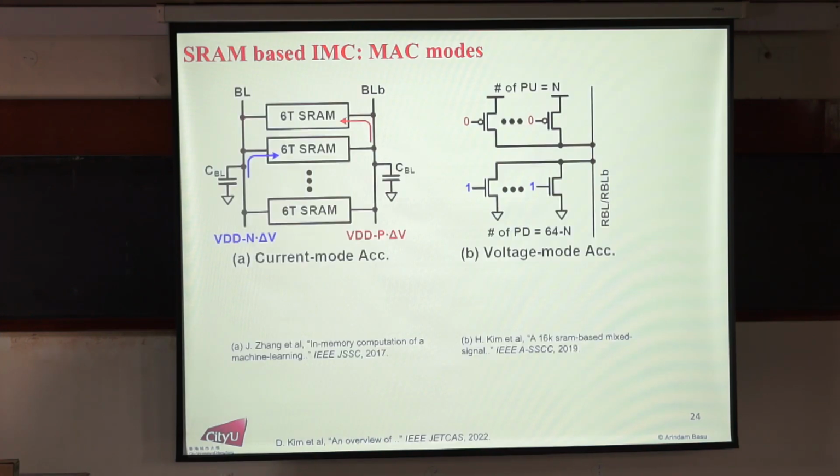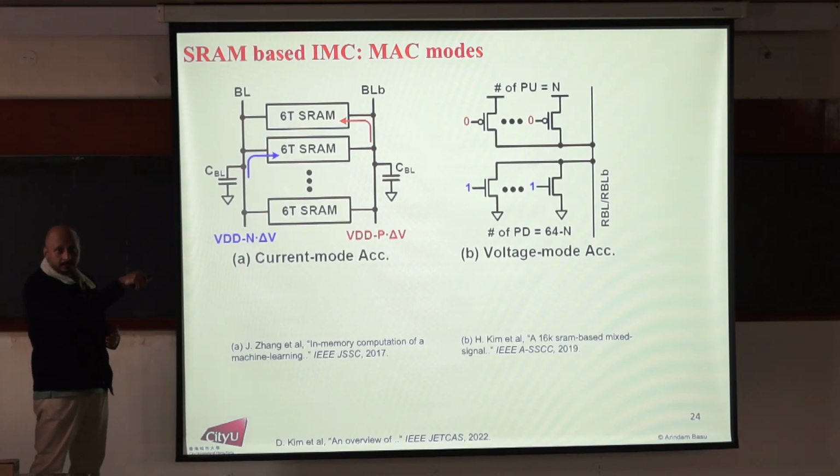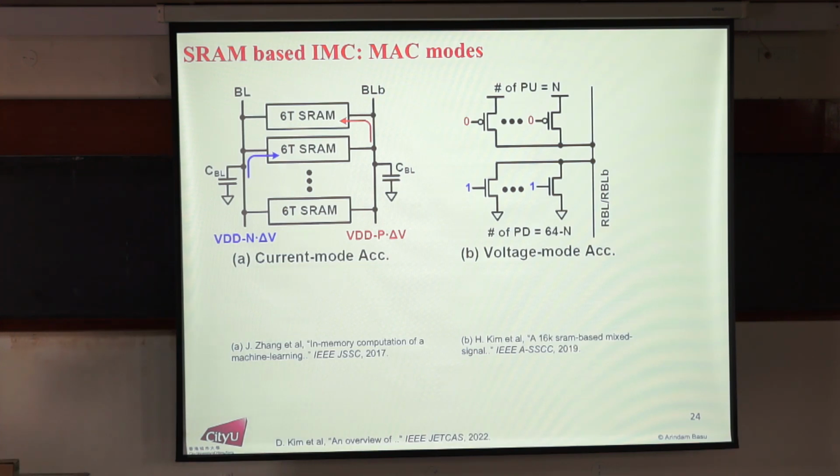This one won't, but the other one will, because here PMOS and NMOS are fighting together. This one will have a huge amount of short circuit current. Yeah, that's a problem. So you have to only enable it for a very short time, read out your outputs, turn it off. No, of course not. They have designed it in that way. These devices are very tiny. So you have to be careful when you design these.